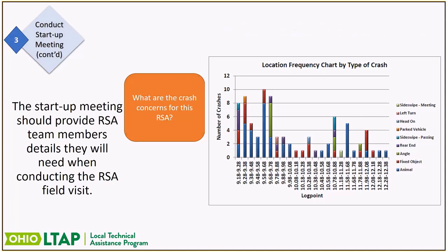Well, what we found with this road when we went out is that the areas where the animal crashes were more severe, this road was actually on a very flat section of Ohio that you could just see for miles in either direction, but that segment of the road with the increase in the animal crashes, there was a park there that just kind of grew up out of the dirt. There was tons of trees. Part of the recommendations were to look at some potential fencing, because there were just a ton of deer crashes happening in that area.